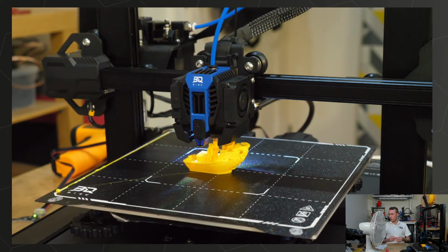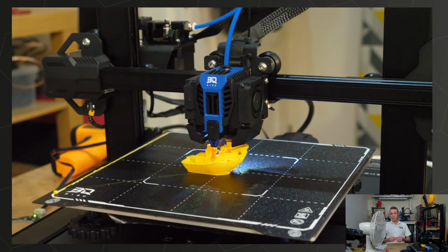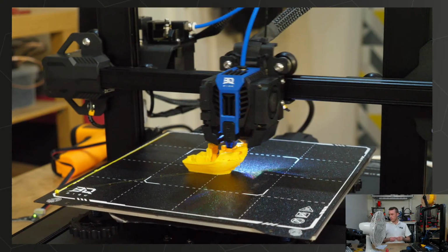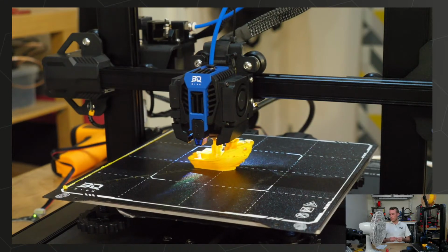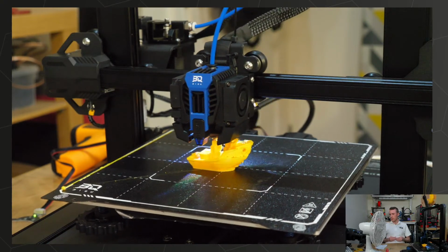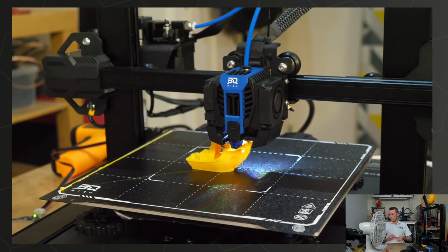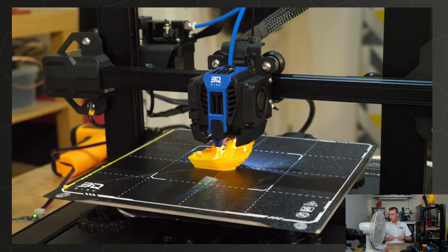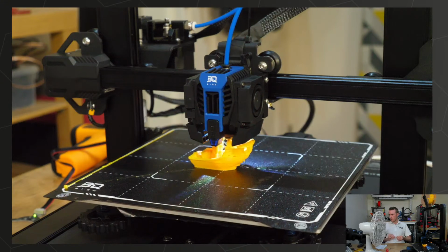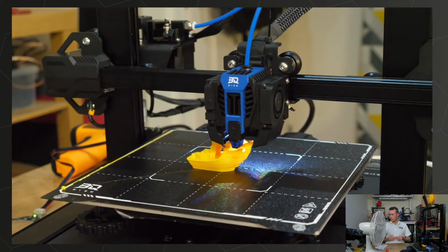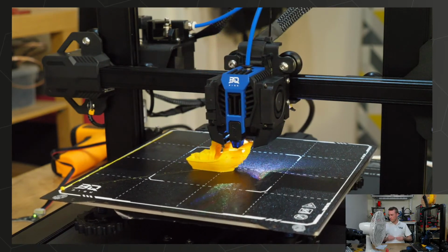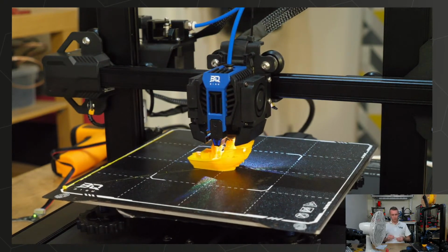Paul, what might be worth trying, I mean it's probably a pain, is to take it out of the printer entirely, use a different SD card and boot it up into something else, a really simple system, because that way you'll see if the hardware is working or if it's software related. Because all the time it's in the printer and connected to other stuff, you've got so much that could be causing problems. And also, don't use Wi-Fi.